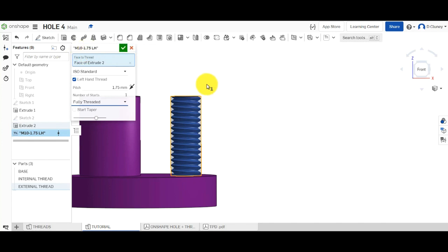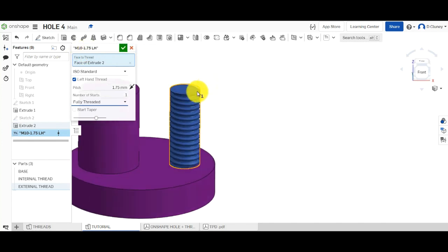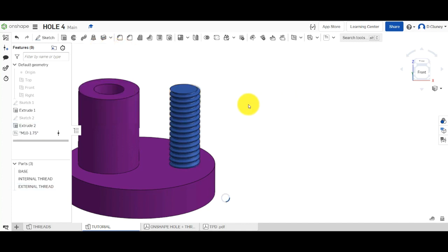it's looking at the initial drawing. If I change the drawing to 12 millimeters and then update to say M12 by 1.75, left-handed thread if I want to, or don't, and then tick it, and it will just leave it as a standard thread, update that.